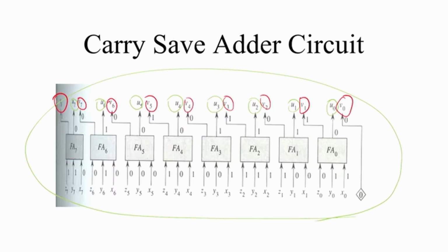Is the input of the full adder restricted to only 3, like a 3 pin full adder? Full adder means it's a 3 bit full adder. Oh, okay. It's just a module, right? Yeah. Just an XOR circuit and 3 AND gates and an OR gate. It will generate the sum of 3 bits and the carry of these 3 bits. Fair enough? So this is the construction. I am showing this slide to show that this entire operation will take constant time, or order 1 time. 1 is constant.